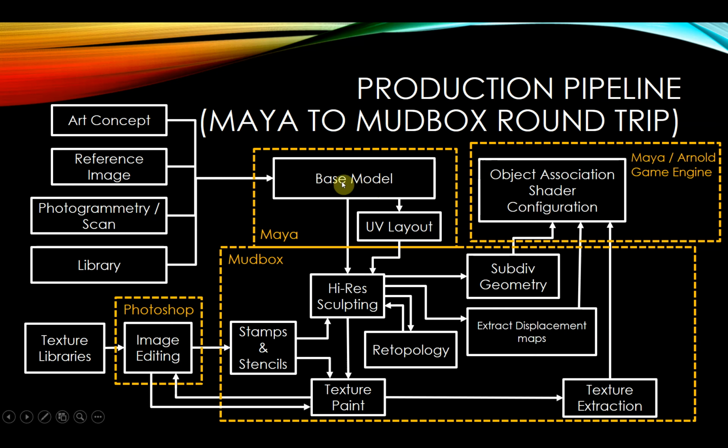The reason for that is that what Mudbox does, in order to support the really high-res details in your sculpt, is subdivide the model lots and lots, to the point where you have millions and millions of faces. So it subdivides right down multiple levels. Obviously your model needs to be able to cope with that, otherwise it won't work inside Mudbox.